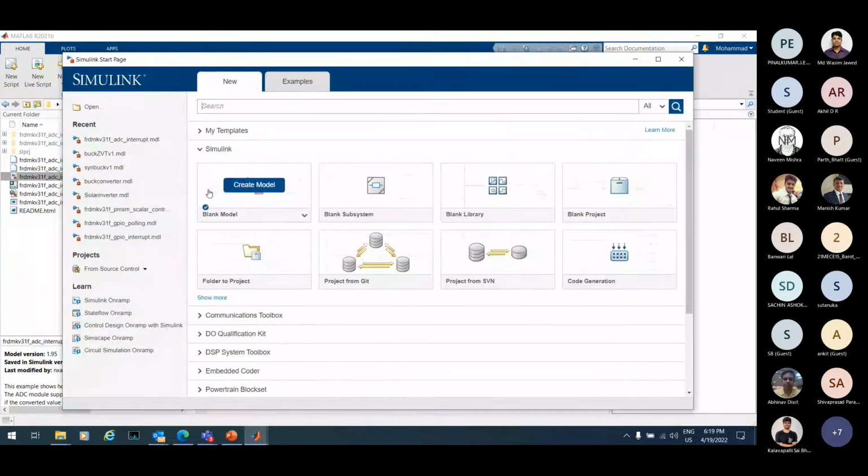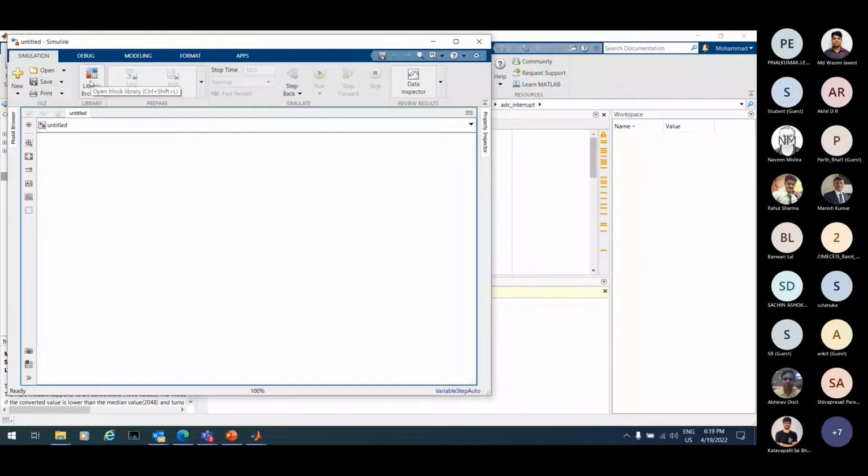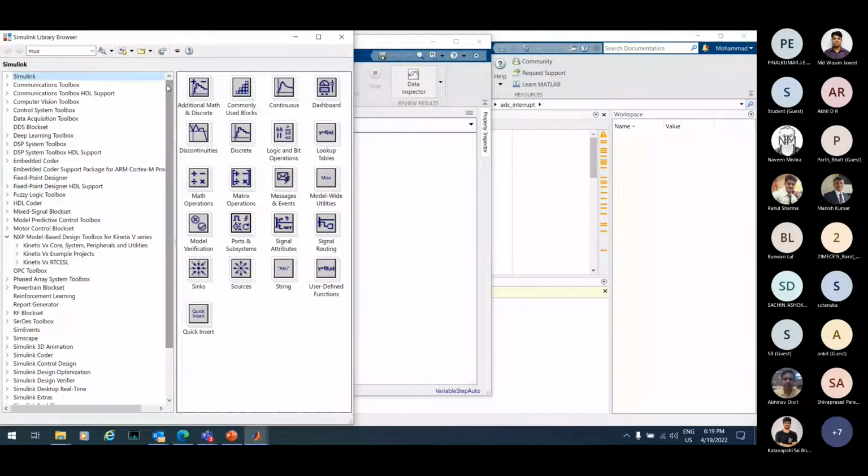Now to Simulink. Simulink is actually from MATLAB, where you do these simulations, and let's say go to the blank model and see in the library, the Simulink library will give you all the things in block format. So there are two ways that you do simulations for your systems, the control systems or whatsoever it is. One is that you start picking up those blocks and put them together and do simulations, or the other way is that you write code for all the simulations that you want to do, and then run the simulations. I'll show you both.